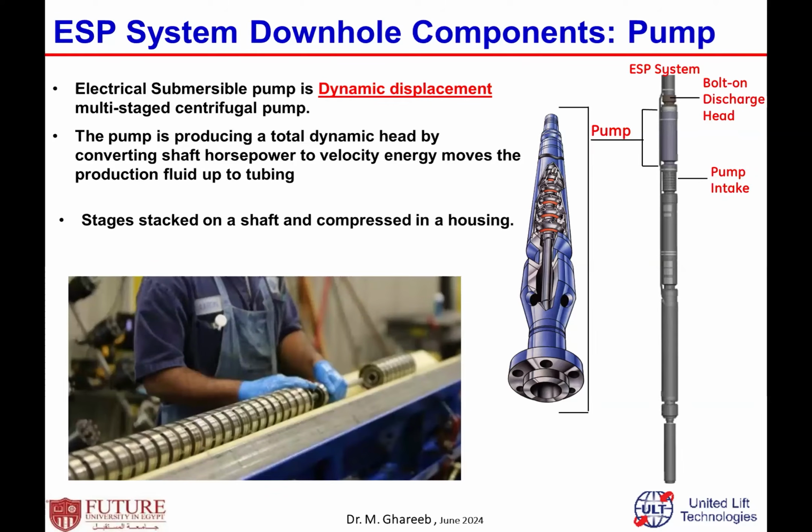Each centrifugal pump has more than one stage. Each stage, as I said, produces a certain head for the fluid. Then the stages are stacked on each other, depending on how many stages I need, based on the design and selection. The stages are stacked on a shaft and compressed together in a housing, and this is what we call the subsurface ESP pump.